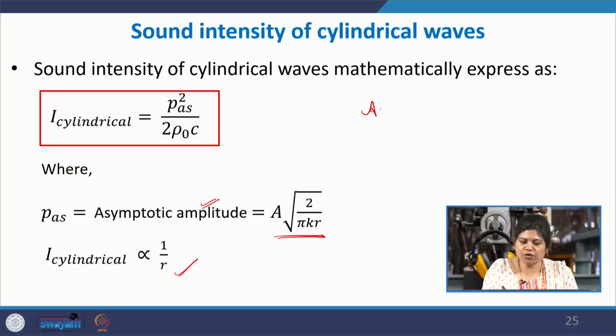So, in some ideal situation in a machinery setup, suppose we have one source that is spherical, another source that is cylindrical, and another that is a harmonic plane source. The harmonic plane source is more dangerous. Why? Because there is no attenuation, no matter how far away you are. So, that takes priority over cylindrical and spherical sources. A spherical source will automatically attenuate over distance, and the same goes for the cylindrical.